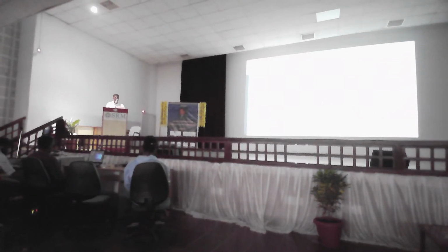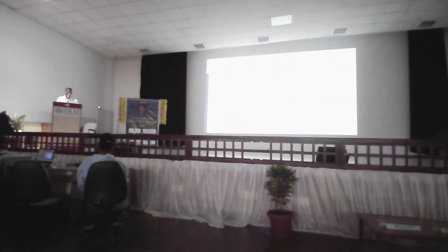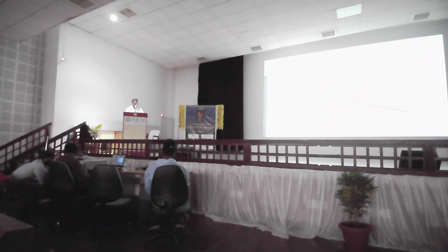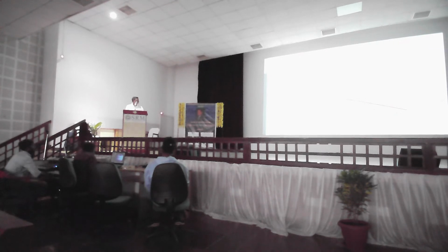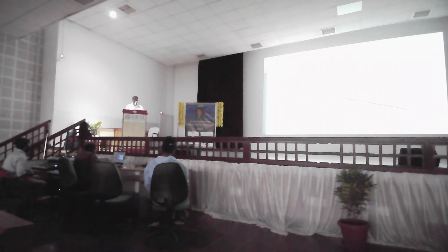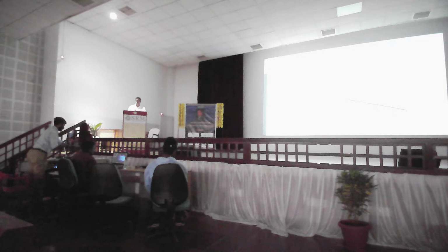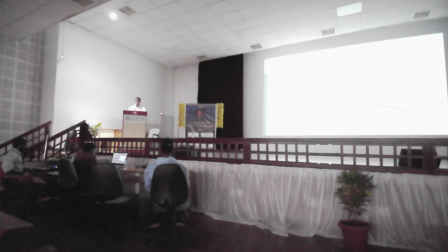This curve is from API. This curve comes from various experience, maybe experimental methods they define this curve. So you can see here the number of cycles to failure is more if your stress range is less. You have to calculate the actual number of occurrences because we have all the environmental data, and the wave period, everything will be there. We can get the number of occurrences for 1 year, so we can extrapolate that for 25 years or 30 years. From that we can define the operating life of our structure. And this is pre-service analysis.